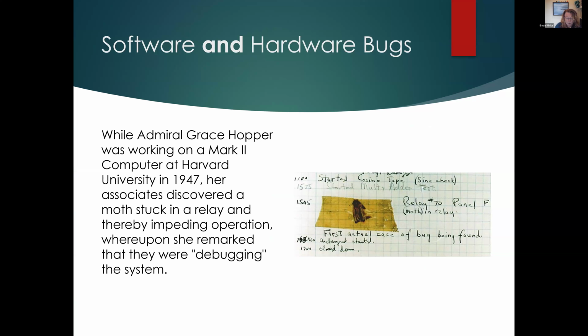However, in embedded software, the bug could be my software. It could be the hardware, which may have errors in design. The board, which may have an error in manufacturing, like a solder glob or a loose wire in a connector, or a piece of dust that landed on my board overnight. It may be a power supply that's failing, a processor with a known bug, but I haven't looked up the errata lately, a compiler that was really designed for assembly and not these fancy C++ features. It may be my software, or it may not.